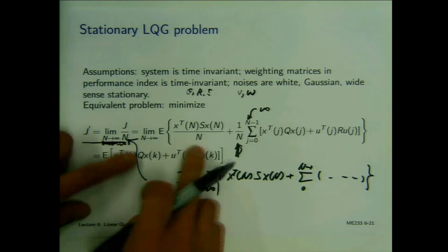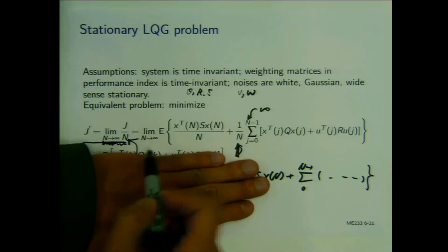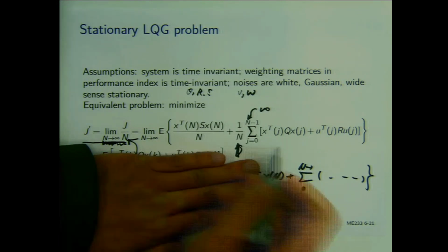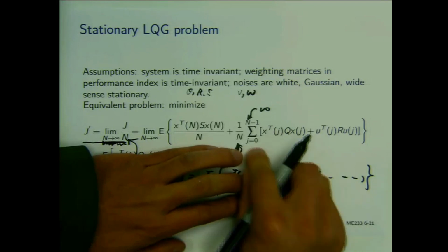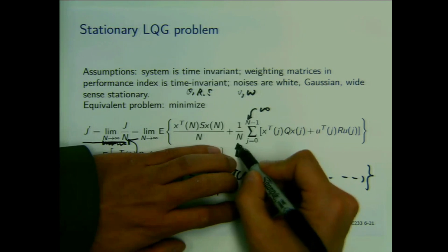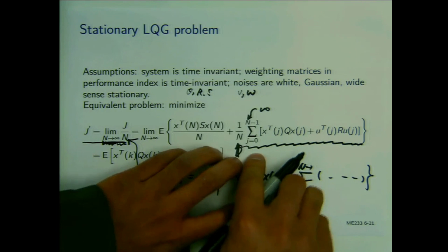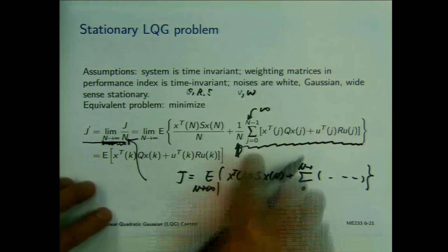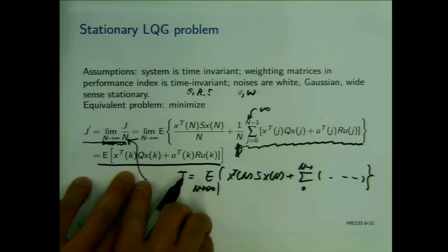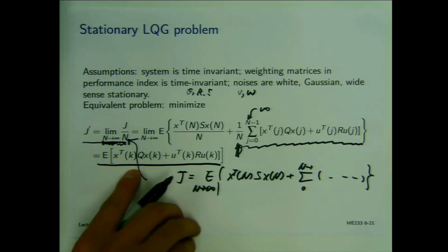So we needed this 1/N here, divided by N. And it turns out the result becomes very nice if we do this. Think about a stationary case: if everything has settled, and I divide this summation by capital N, then due to the law of large numbers, this becomes the expectation of the current optimal cost, the current second order quadratic cost.